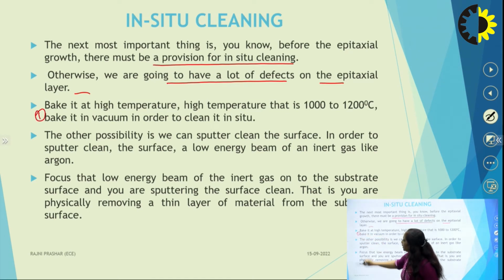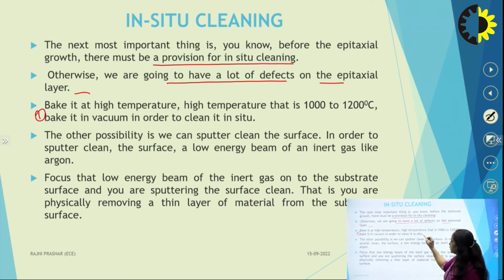So the first method is to bake the wafer at a high temperature, up to around 1000 to 1200 degrees C. Another is that we can sputter some gas on the wafer that will clean the contamination present on the wafer.